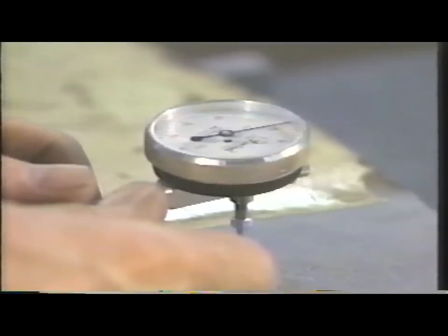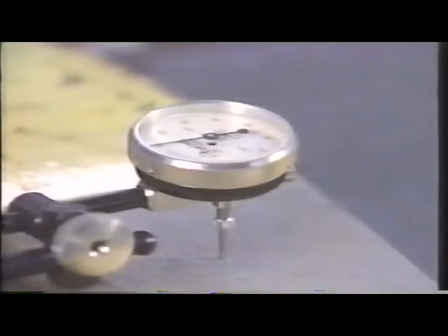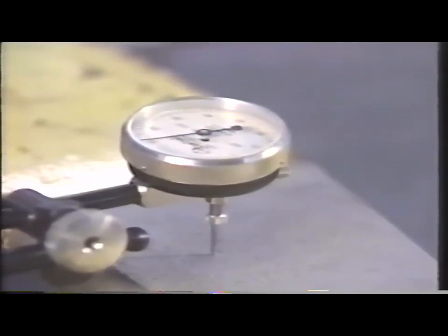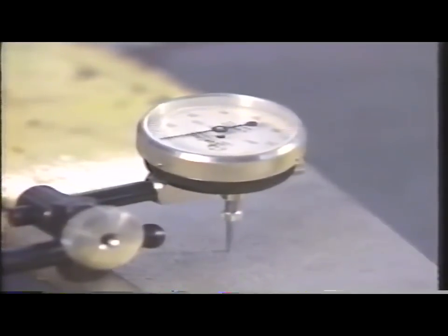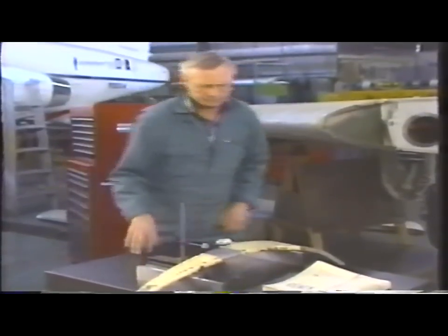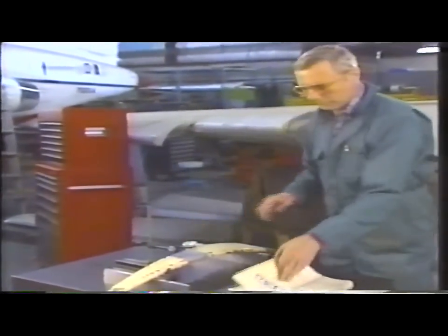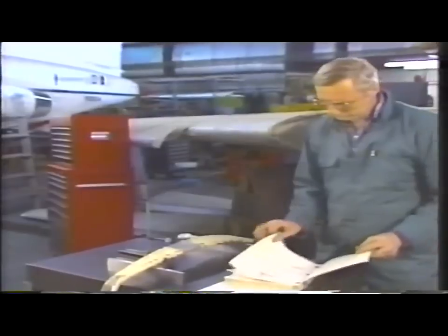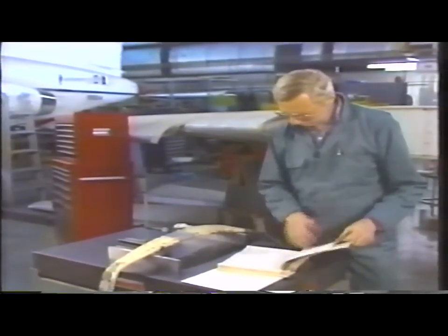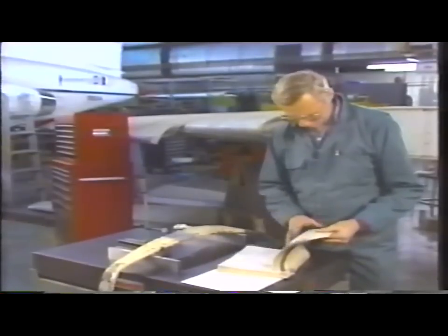First, you must zero the gauge by measuring a non-damaged area. Then take a reading from the deepest pit. This reading represents the amount of material lost to corrosion. Now that you have measured the extent of the corrosion damage, you must compare this last figure with the manufacturer's predetermined acceptable rework limits. If the damage exceeds the limit set by the aircraft manufacturer, the affected part must be